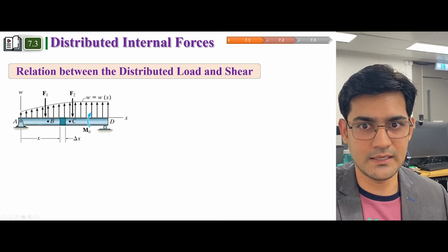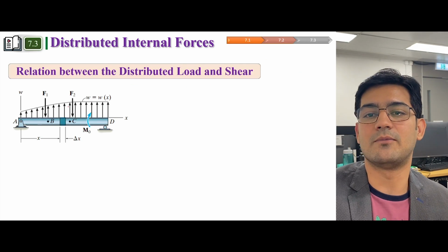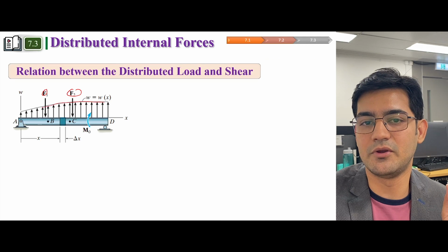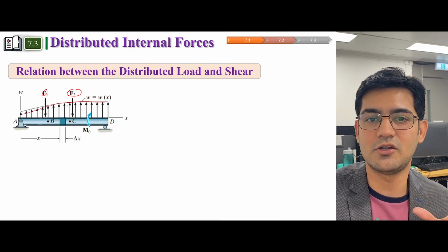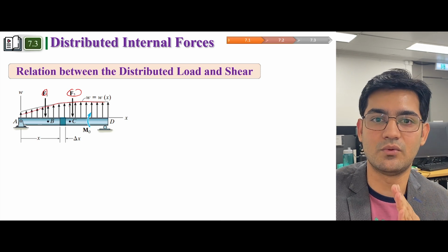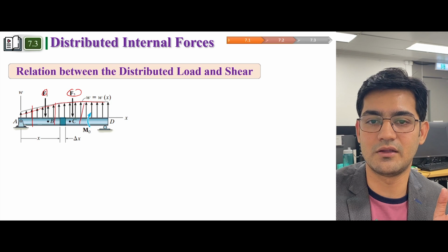So what I mean to say is that imagine you have this type of loading condition. You have two concentrated forces, you have a distributed load. So it gets very complicated to do the method of sections and calculate the equations, because then you have to cut a section here also, then here also, and here also.